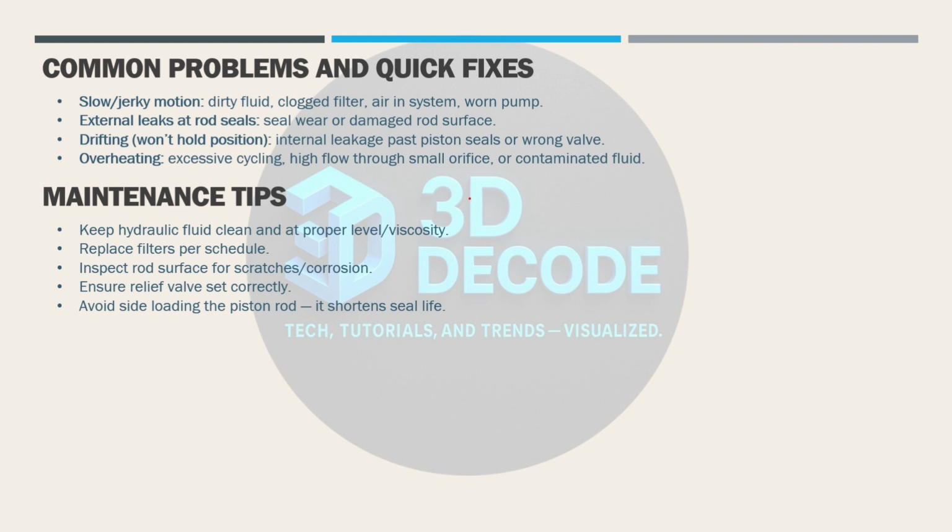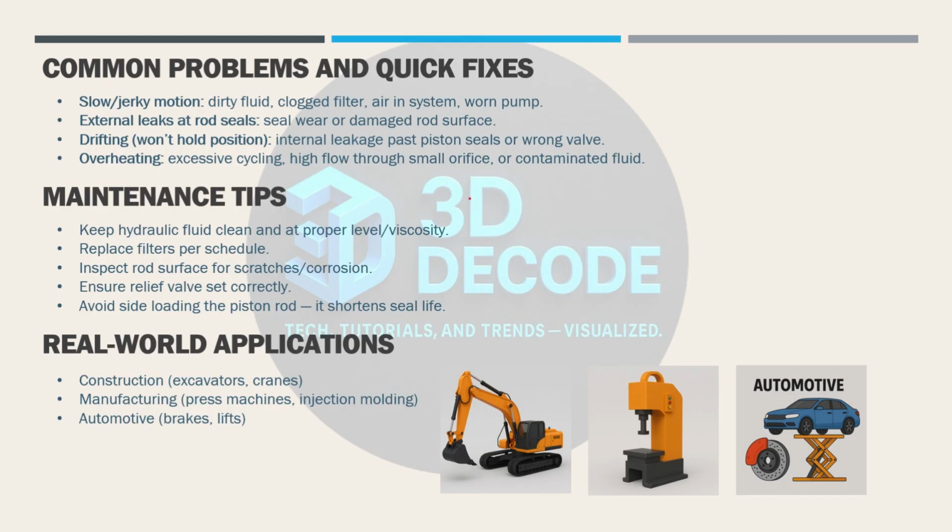Maintenance tips. Keep hydraulic fluid clean and at proper level and viscosity. Replace filters per schedule. Inspect rod surface for scratches and corrosion. Ensure relief valve is set correctly. Avoid side-loading the piston rod, it shortens seal life. Real-world applications: construction, excavators, cranes; manufacturing, press machines, injection molding; automotive, brakes, lifts.